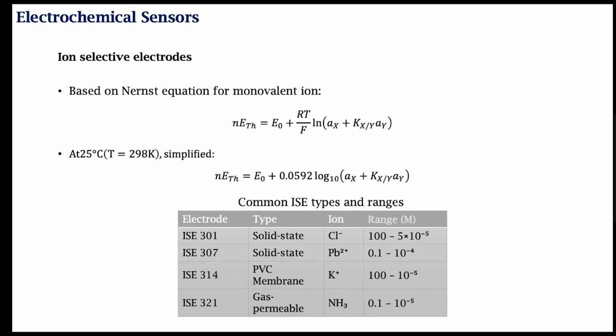And there are different types of these ion selective electrodes that we see, and some of these are useful to measure certain types of ions. Some of them are used to measure chloride ions, some of them are used to measure potassium, etc. And again, once you use a reference electrode such as the silver electrode as the reference electrode, then I can make the measurements with millivolt accuracy, except that I will still need a high impedance processing circuitry.